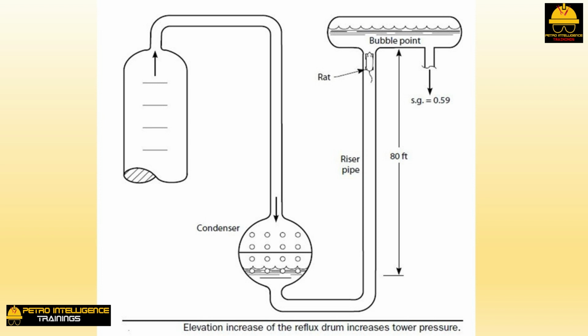The vapor flow rate to the condenser would then be constant. To condense the same flow rate of vapor with a shrinking exchanger surface area, the pressure of condensation must increase. The tower pressure would also go up as the condenser pressure rose. Forget about the rat. I made that story up.